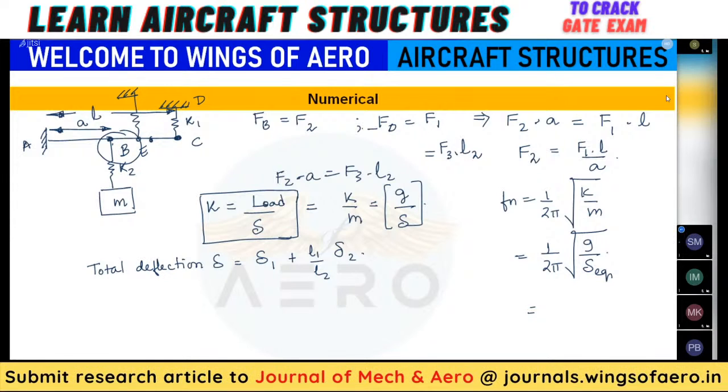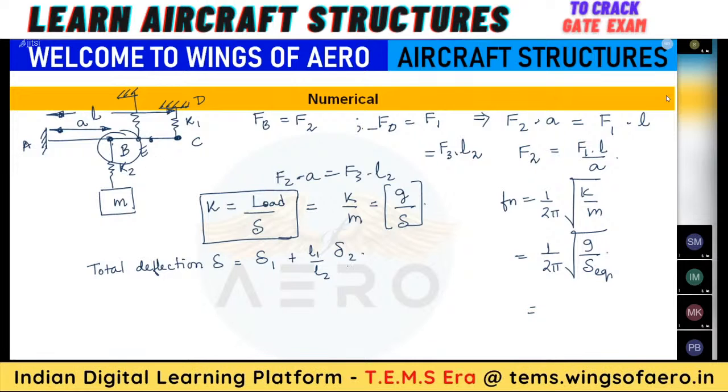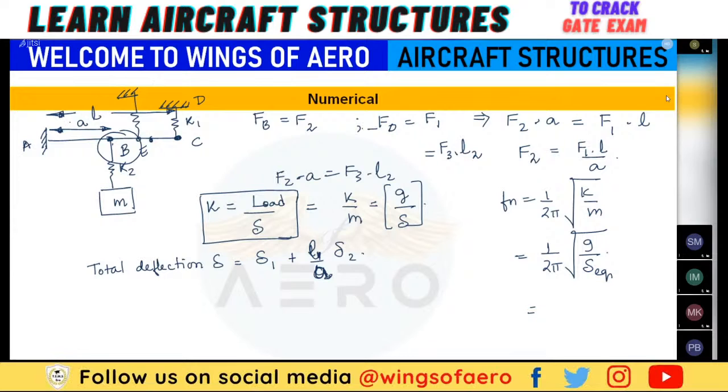Ma'am, how do you write this total deflection delta equal to delta 1 plus L1 by L2 delta 2? There is a derivation. That's why I said there is a derivation. Whenever this kind of problem is there, sorry, here it won't be L1. Here it will be L by A. The bigger one divided by the shorter one with respect to each other.